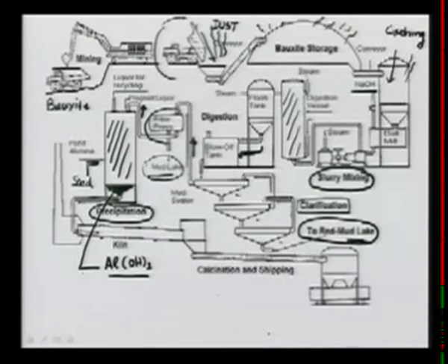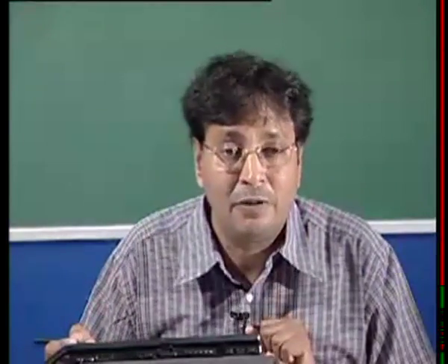Here we have the aluminum hydroxide that is passed through the kiln. Kilns are rotating tunnels. Let's make it a little rotating to indicate the arrow. The kiln is really rotating, and then we are supplying the heat through a furnace. Supply heat, and most of the time we don't use coal or something, because coal will make our alumina very impure.